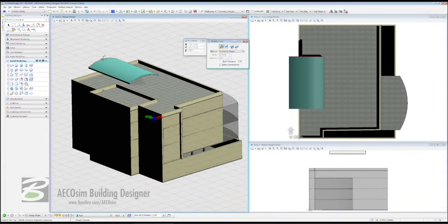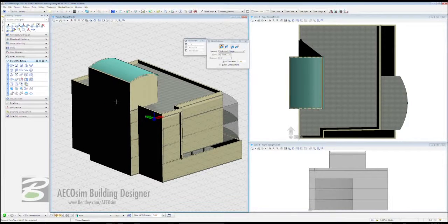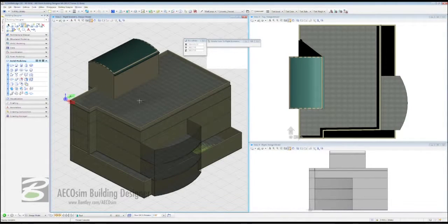With that, we need to click on our solid that represents our roof at the moment, then move off it and left click, right click, and then just come in here and click once. And then just move around the walls, and there you have it. There is our curved surface, as our walls have now been projected up to the underside of that curved surface.